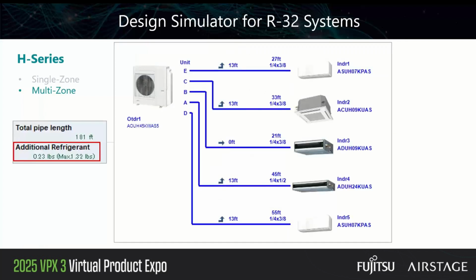And what about this? Don't you think this is a nice printout that you could print out, hand to your installers, and they know exactly what goes where in terms of the piping? You can provide estimated pipe lengths. They can cross it out and put in the actual, then we will have a permanent record of the actual refrigerant charge. So there's no guesswork on the pipe diameters or what unit goes where, which connects to what port.